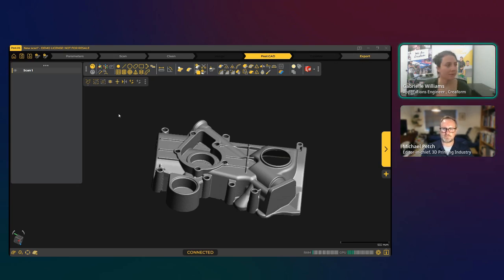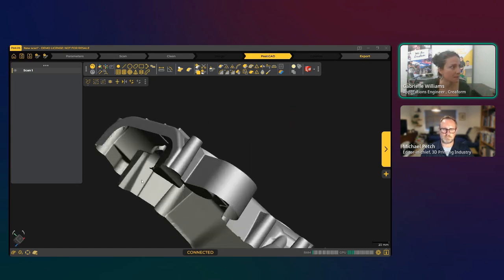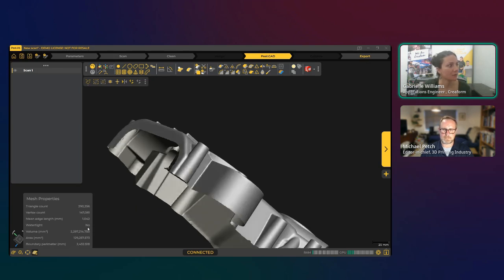Yes, absolutely, there is. So here, there's a few things you can check just to see first. Well, obviously we know this one isn't watertight because we can see the inside of it here. But if you thought maybe it was, you can always go over here and check if it's watertight, and it will say yes or no here. Second, once you've checked on that, there is a tool right here, watertight remesh.